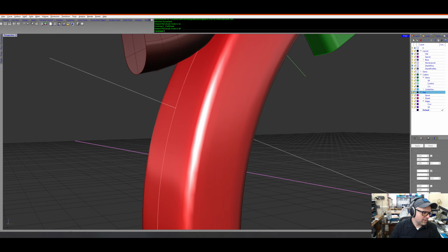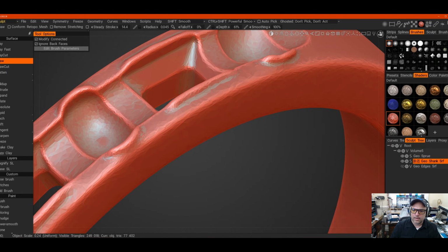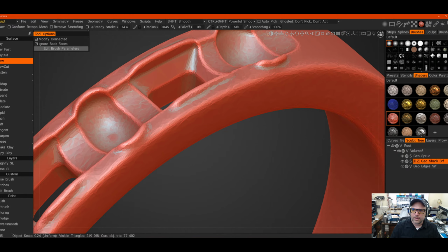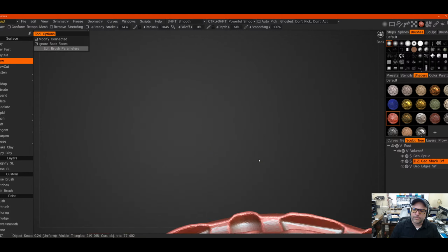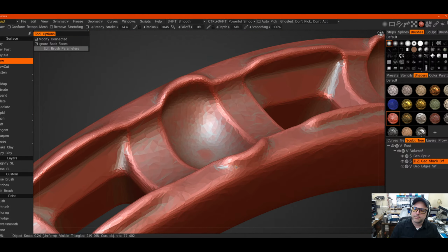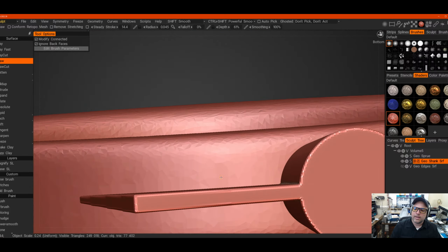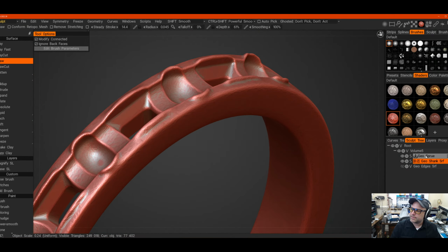Same concept, but completely different by having this, and it'll say right here, double click to activate. Double click. Okay, I will do it the long way around and drag it to 100%. Okay, so this is giving me more contrast between where I have changes in angle. So this is good. I decimated 90%, got that down to, what was it, 77,000 triangles.